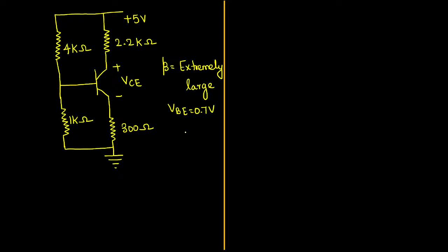And now the question is, IC and VCE in the circuit shown in the figure. Actually the question is, operating points are dash. Identify the operating points. You know which term is called operating point, and you also know how to solve this type of question. If your base terminal is simply connected with a single resistor, then that will be fine. When we are having two resistors, then you have to Thevenize the circuit, find out the Thevenin voltage, Thevenin resistor, then proceed further.